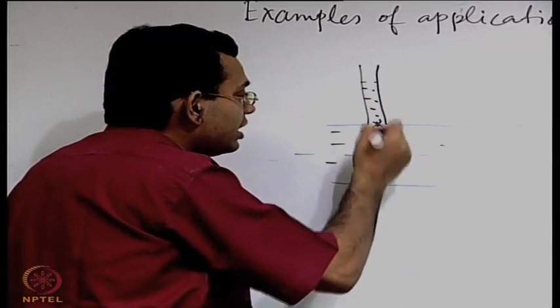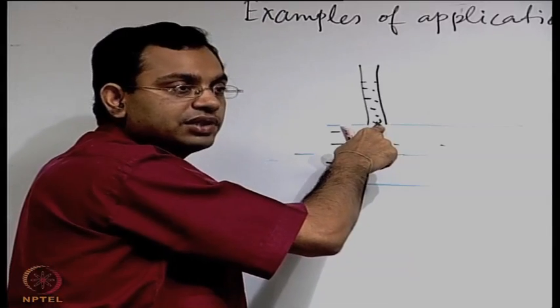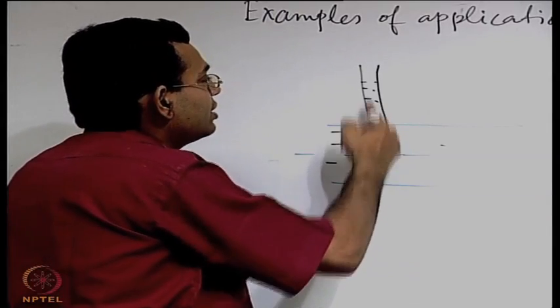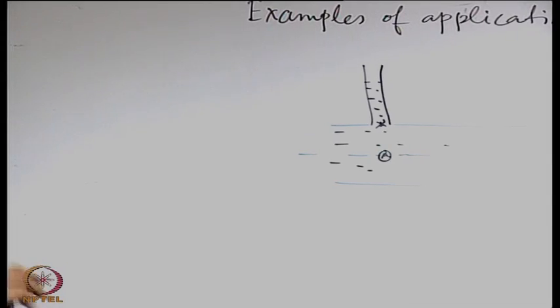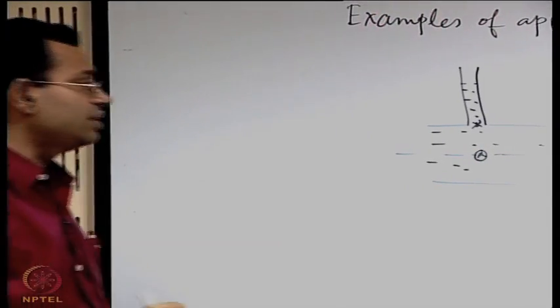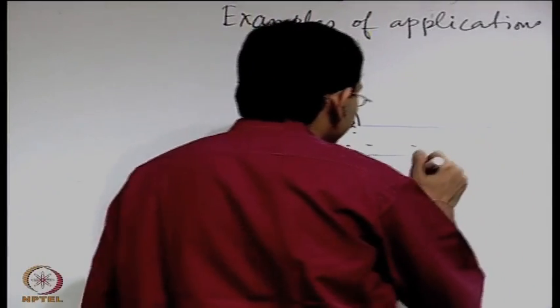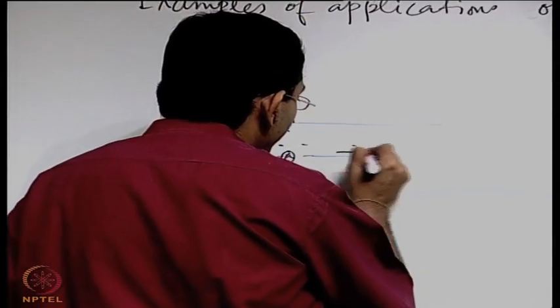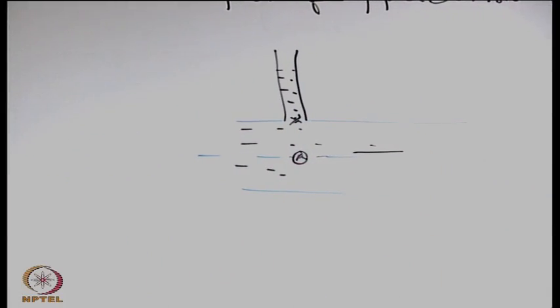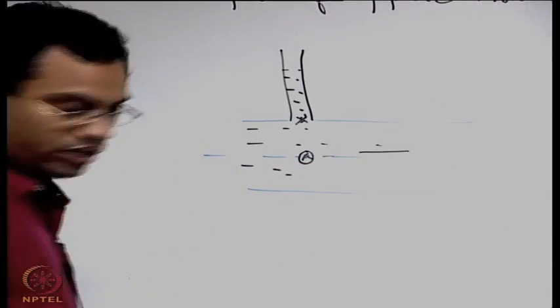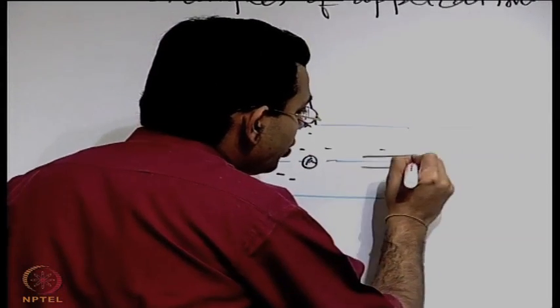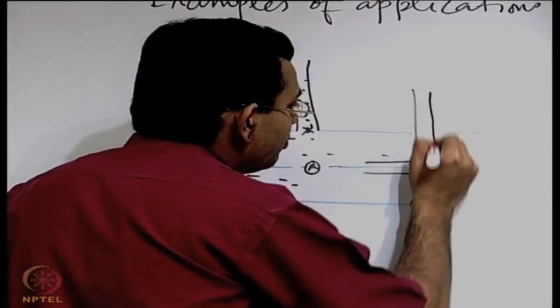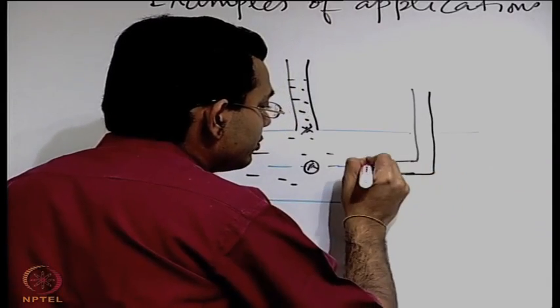So whatever is the pressure here should be the same as the pressure here. So then this is an indicator of the local pressure. Now say we are interested to have an indication of the velocity. So for that what we can do, we can have another tube where we make a penetration in the wall, but before that we have the tube directly confronting the flow.